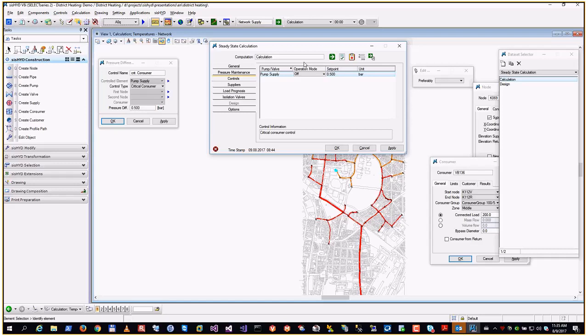And for a different speed of the pump, it goes down, and if it's higher, it shifts. This maximum point shifts a bit to the right. So this is for different speeds. And when we have a mass flow, and we know the speed, we can look up the delta P. So if you specify speed, we need such a curve. If you do not specify this curve, we have some internal one, and it will just suffice the control task.